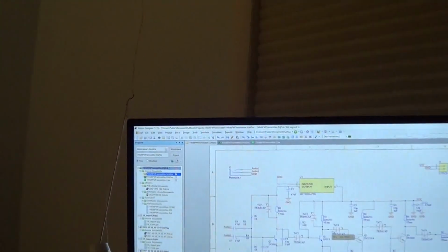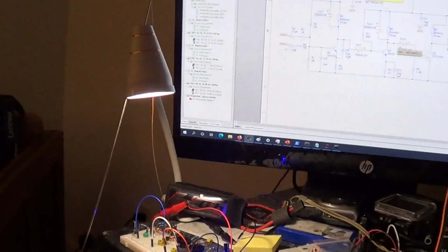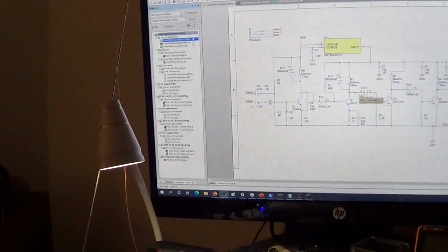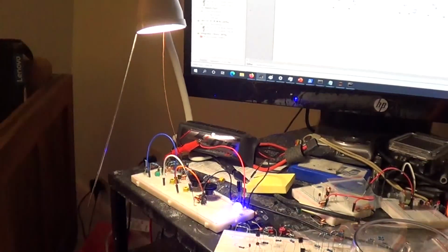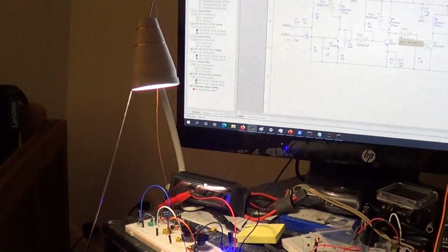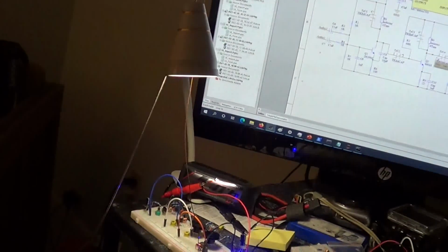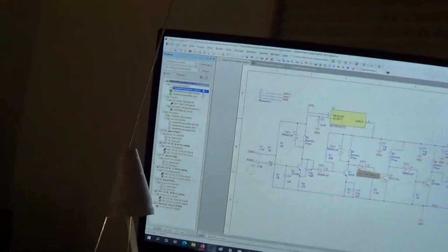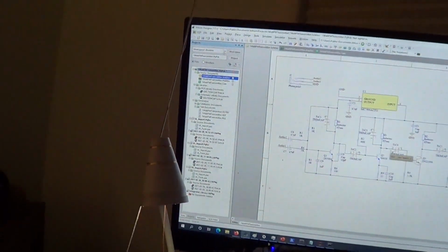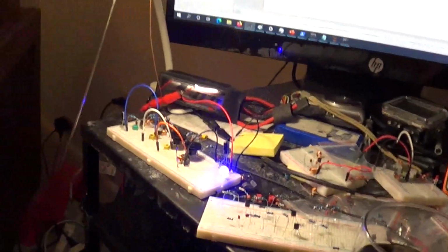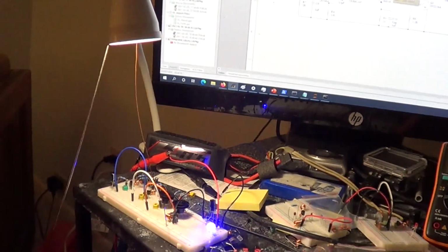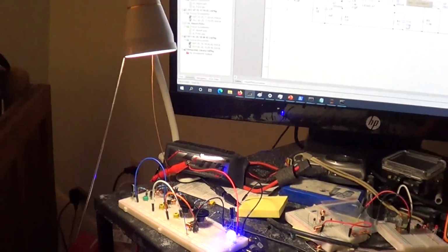The copper cable is this long because that's a quarter of a wavelength. In our case, our signals are around 100 megahertz, so you can calculate the actual wavelength based on the wavelength equation. We use that formula to calculate the length of the antenna, and we only use a quarter of a wave. I don't want to go into that detail, but you're more than welcome to research antenna design.